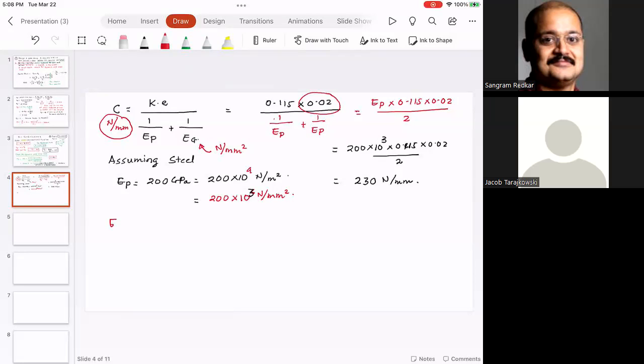I'm going to find out sigma E. What is the value of sigma E? To find the value of sigma E, you have to go to a table 28.8, and in 28.8 you have various grades, and there is flexural endurance.